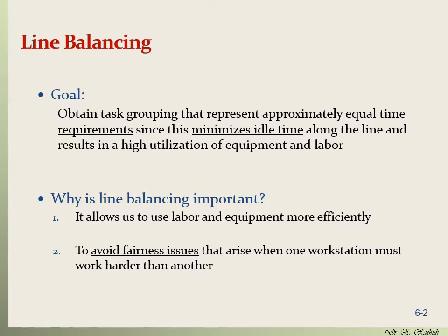Why is line balancing important? For mainly two reasons. The first is that it allows us to use labor and equipment more efficiently. And second, to avoid fairness issues that would arise when one workstation must work harder than another. So this is a labor and personnel consideration.